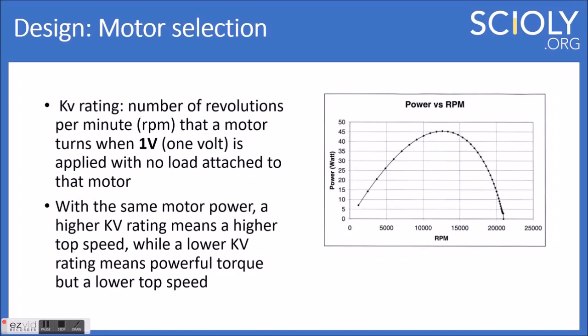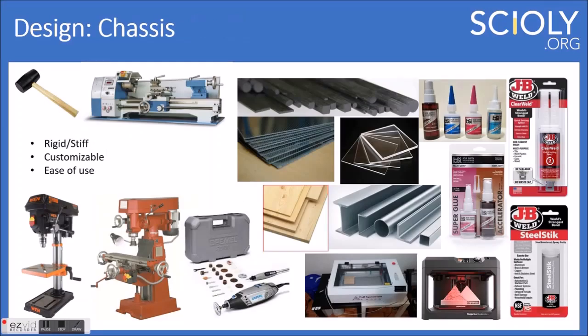That's not really given. So just taking a raw RPM, if you find a motor online that says 4,000 RPM, it doesn't really mean that it's going to be 4,000 RPM once you're running it and it's attached to a gearbox and a motor and wheels and everything. It's not going to run at that same RPM anymore. It's going to be lower. So you can't just take those RPMs and do your calculations based on that. You have to figure out, okay, what RPM would it run with a load on it? And that is not something most manufacturers will give you. So it might be something you have to determine on your own.